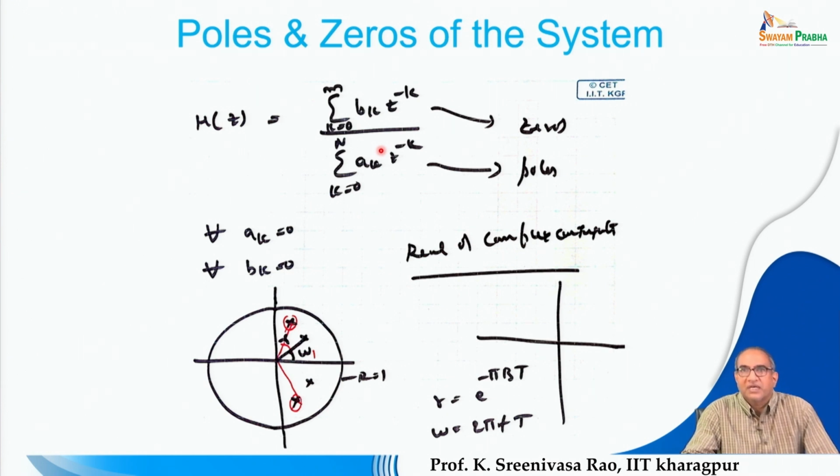So, in the case of speech, instead of approximating the system as a pole-zero system, for the sake of simplicity we will approximate it as an all-pole system, because in an all-pole system the numerator polynomial has all coefficients equal to zero. Therefore, we will consider only the denominator polynomial, and then the analysis of the system will be somewhat simpler and easier.